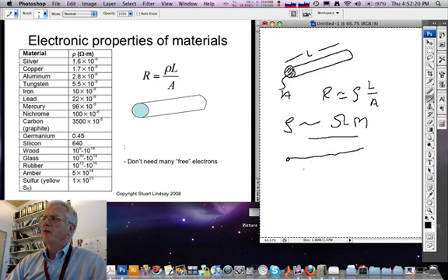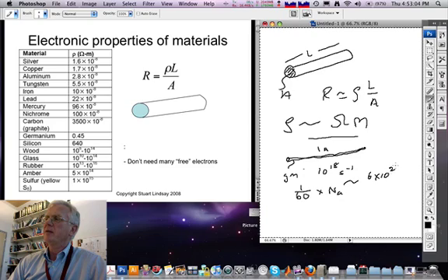So if you imagine that this is the wire from your outlet on the wall to your electric kettle, and it's carrying a current of, let's say, 1 amp, this is equal to somewhat more than 10 to the 18 electrons per second. There's probably a gram of copper in this wire, and so the number of copper electrons is going to be roughly 1/60th of the atomic weight of copper, which is approximately 60, in 1 gram, times Avogadro's number. If each copper atom gives 1 electron, it actually gives 2. That's 6 times 10 to the 23. And so you can see that something like 10 to the 22 electrons are available in this wire, and only 1 in 10 to the 4th passes through the wire in heating your electric kettle.